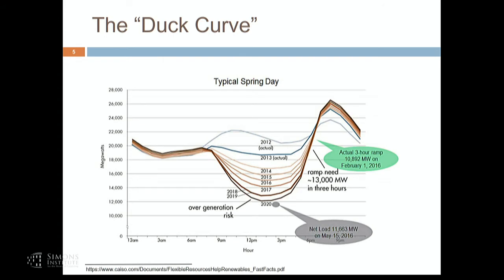So we need somehow to monetize, to give them an incentive to respond to signals, and that's why we pay for those generators that are capable of moving fast. We want to encourage them to move fast, or to install governors that enable them to move fast, and that's why we pay for ramping capability. So we create new products that incentivize their behavior to respond to the needs of the system operator. Now, we can do it on the demand side as well.